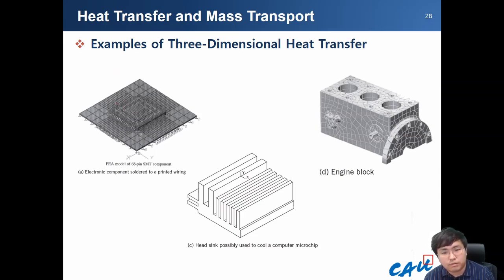If you have some semiconductor device chip, IC chip, or heat-cooling microchips, in this system we use the FEM method after discretizing the solid structure. We can apply our governing equation and boundary conditions properly, and after computing, you can obtain the temperature distribution.